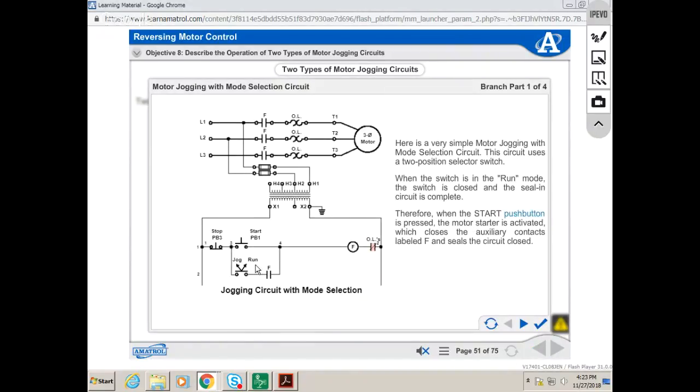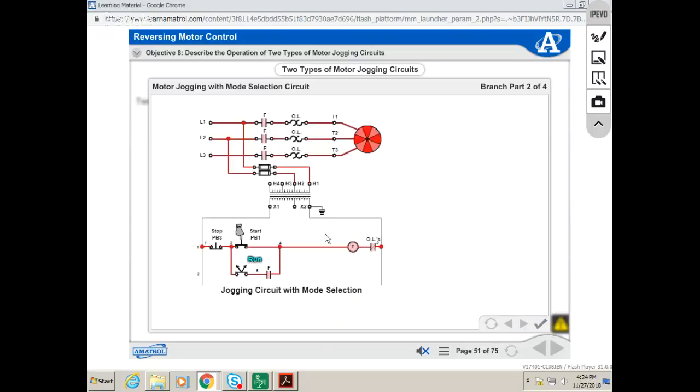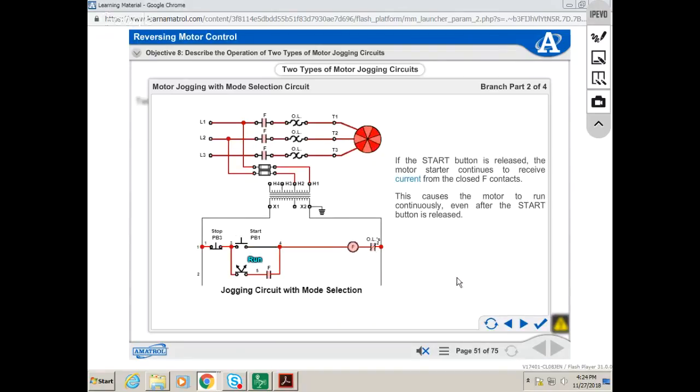Then we would have what I just showed you before with this simple jogging circuit here. Same principle as what we did before, breaking the latch there with the jog. When we hooked it up before, I made you add a separate jog button. Everybody understand how that circuit's working? There's no confusion about that, what we just drew on the board.